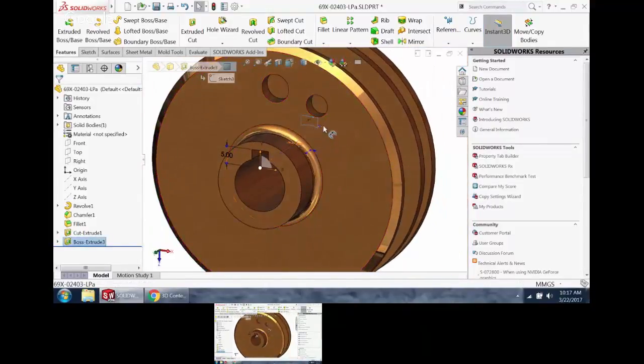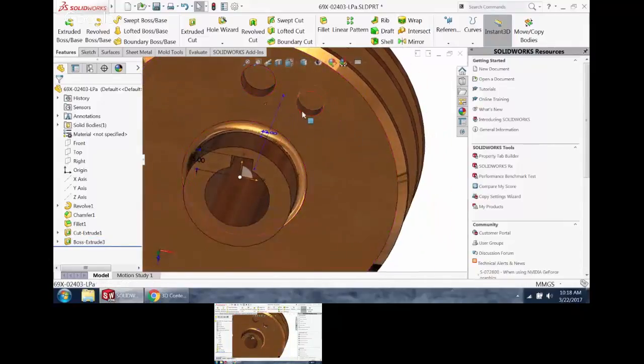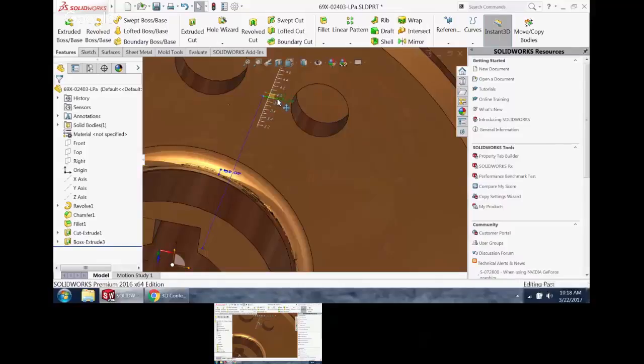And you'll see that as I'm dragging this, I get this scale pop up. If you've ever noticed that, take a look at the numbers here. When I'm dragging them here, they're just willy-nilly, any number that I'm at. But if I hold my cursor over the scale itself, it'll snap to that scale. So it'll give me an exact number instead of just dragging it however far. If the scale is too fine, zoom out. If it's too coarse, zoom in. The scale will actually change with how much you're zoomed in.